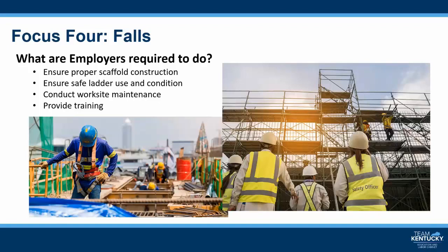A competent person must supervise as scaffolds are being erected, moved, taken apart, or changed, and they also must inspect the scaffolding. A guardrail system or a personal fall arrest system is required for scaffolds more than 10 feet above the lower level. In addition, employers must provide safe access to and from scaffold platforms.